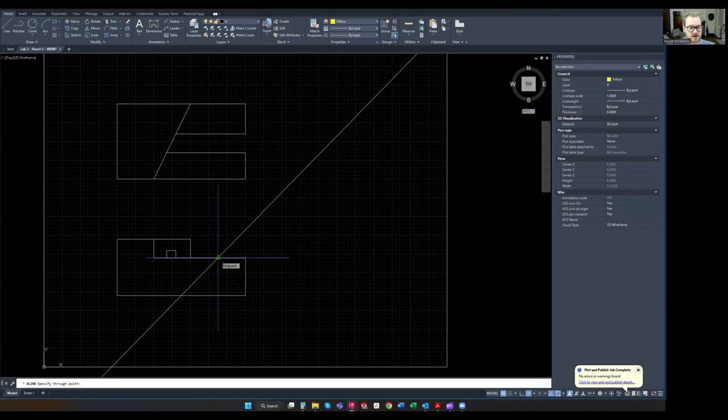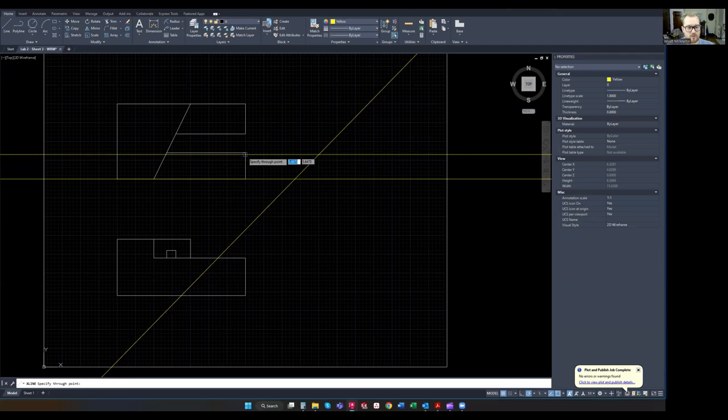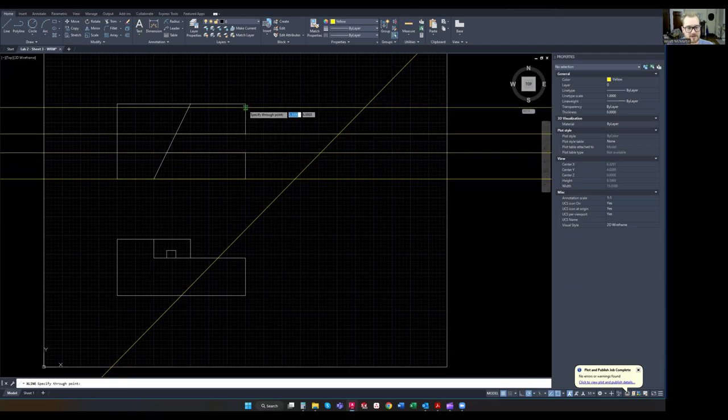And we got our little triangle midpoint, snap it right there. And then take horizontal construction lines, XL enter, H enter, and snap to these 4 points right here, just like this.